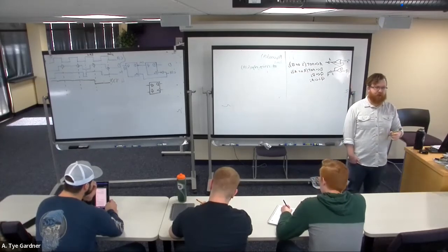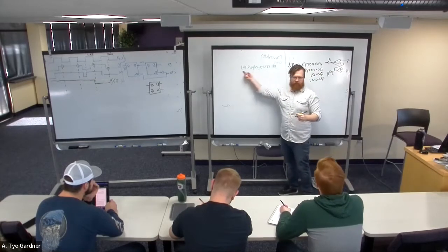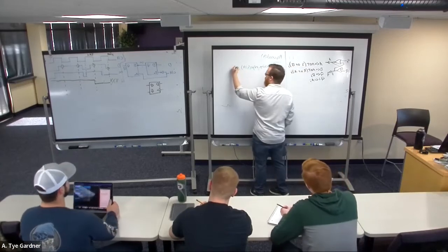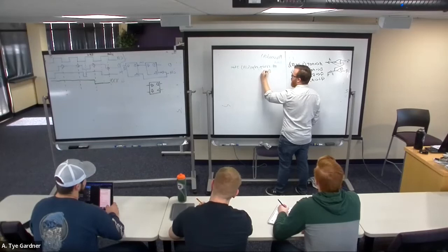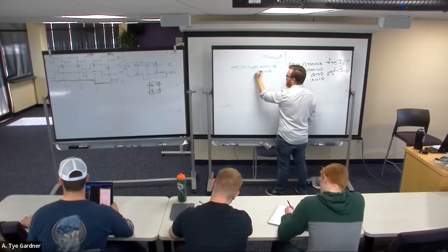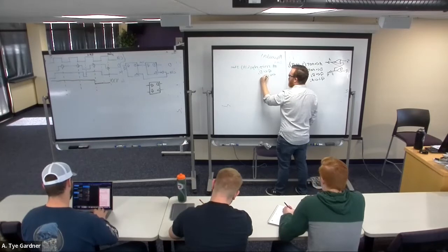This is going to evaluate that if it finds a transition from 0 to 1 on the signal clock, then my output Q gets assigned to my input D.